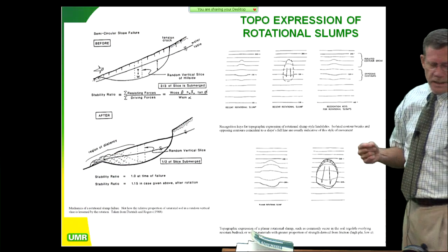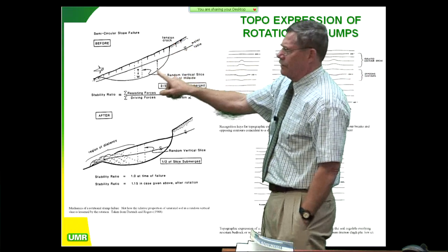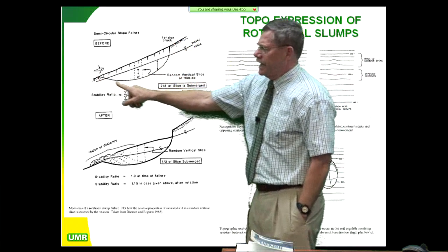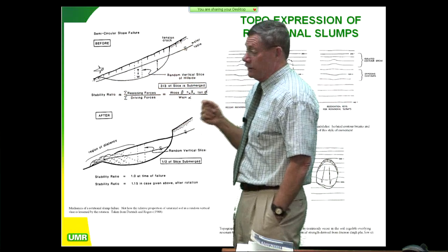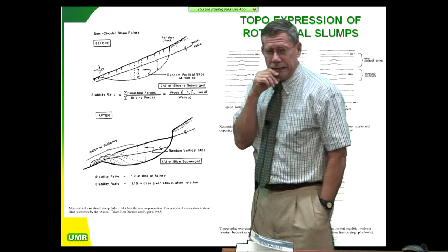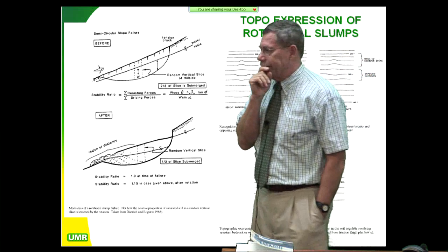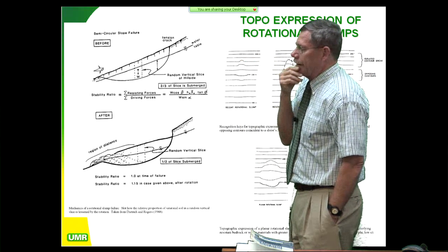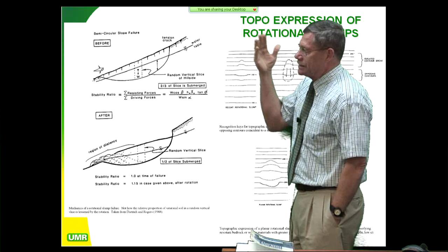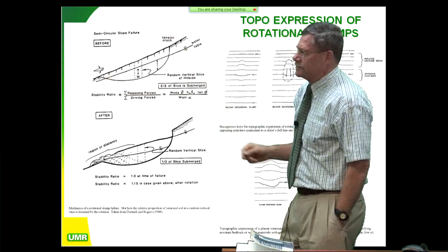Well, if we have a rotational slump, what is going on with this slump? It usually has a log spiral shape. And that was Leo Rendulic's thesis under Terzaghi at the Technische Hochschule in Austria, 1934. Rendulic wrote an article, 1935. It's in German and says the slip surface is not actually circular, it's a log spiral shape, and that's true.